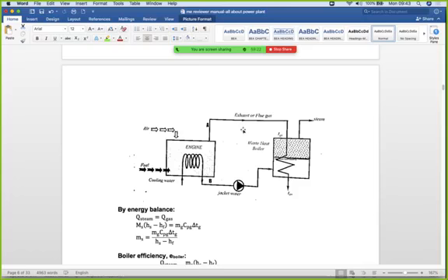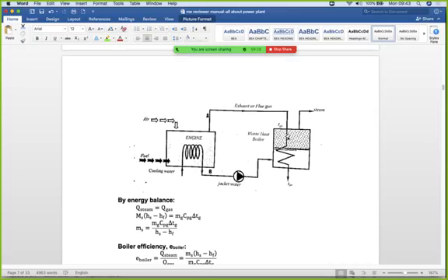The unwanted gas will go inside the waste heat boiler to preheat the water here. So there is entering cooling water passing, and it goes to this waste heat boiler. This boiler is now being heated by the use of exhaust or flue gas. That's why it's called a waste heat recovery boiler.